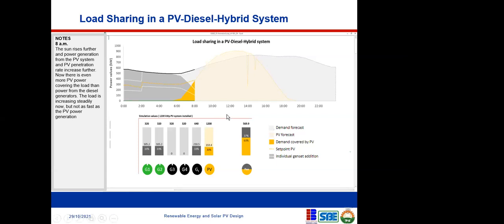So, for example, a shadow might pass through the solar panels, and the intensity of the sun will be blocked, and the energy that is coming from that panel will drop unexpectedly. So when that happens, you need a generator that can pick up that power immediately. You don't have any seconds to begin to start the generator. The generator has to keep running to pick up that power immediately. And that's why you need to keep running these 2 generators to make sure you cover this total energy that is needed.